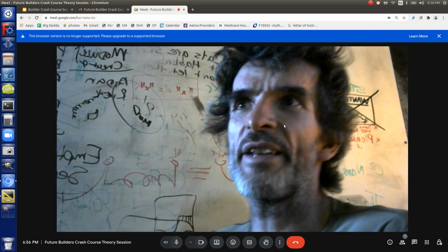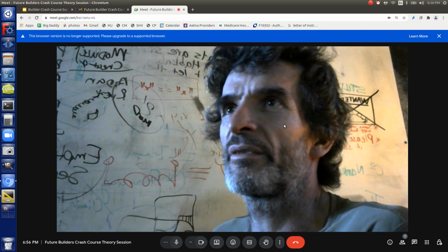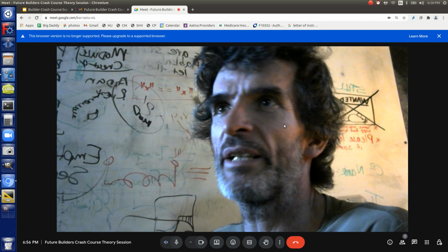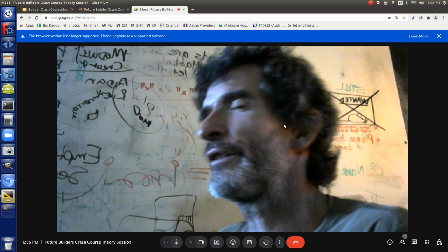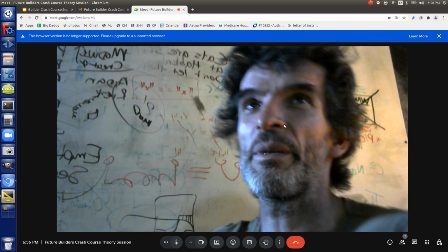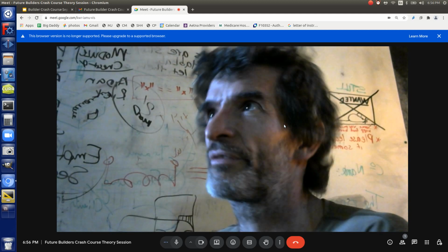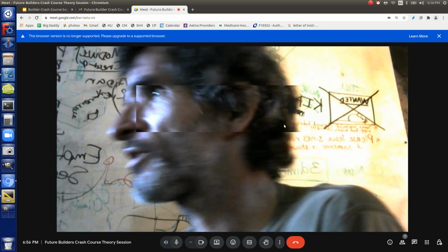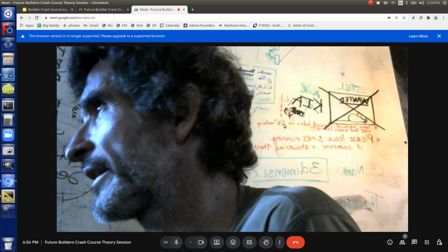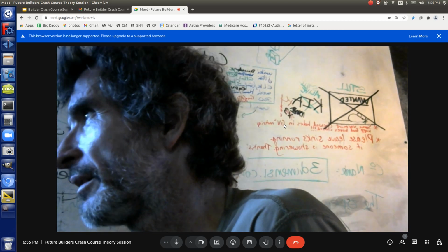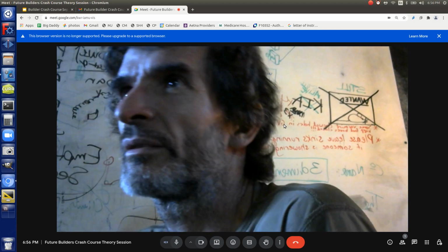It's the limit of the nail and OSB. Let's say the max limit is, I kind of feel, I've seen from experience that the OSB will typically give first. But let's say the OSB gives first. How much are you holding there? How much is each nail holding? Well, we know that nails are good for about 100 pounds.